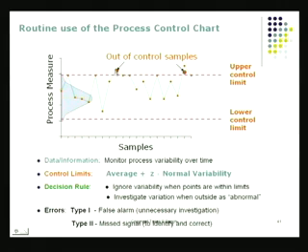Don't second guess. The moment the chart has gone beyond control limit, stop the process and go to something that is called the reaction plan, which is what you construct using the cause and effect diagrams and so on. Then go through your full list of checklists, and check everything about that machine, just to make sure that you will not end up thinking everything is in control and producing products that are off spec.